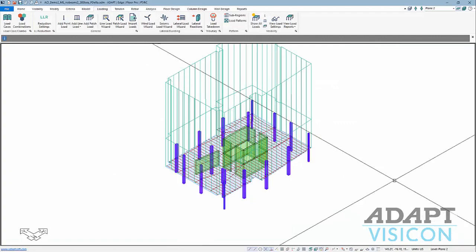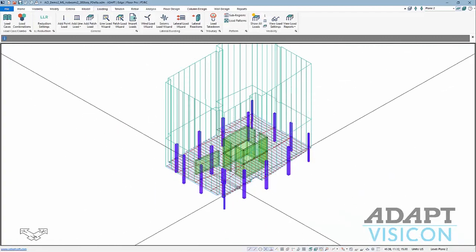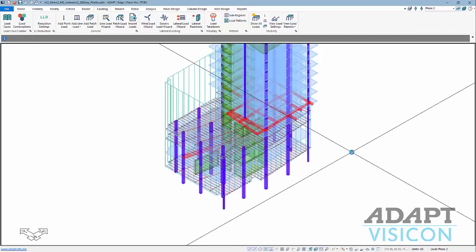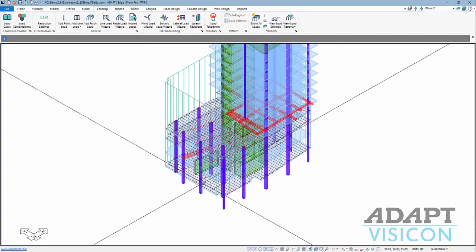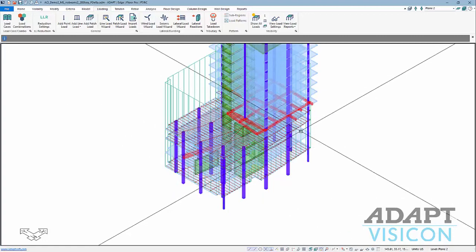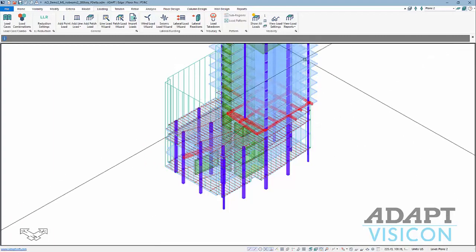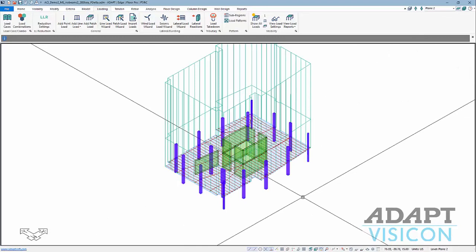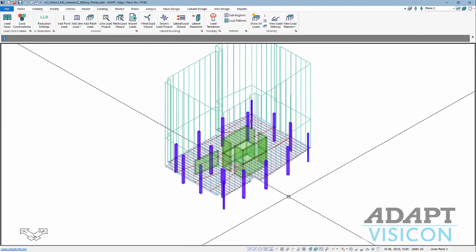So we'll go ahead now, and we're going to be using a PT slab here. This is a single level slab. It's actually occurring on plane 2 of a multi-story structure. So to check punching shear, we can do this various ways. We could actually develop the check based on a global solution of an entire structure, or we can go to a single level and just run that particular level in isolation to check punching.